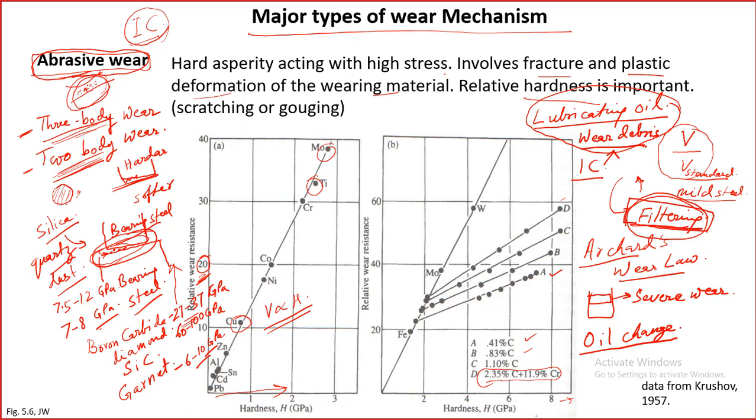Not only wear debris, but there are also some thermal products, some degradation of the oil molecules, and therefore the oil actually changes its color from very golden color to very blackish color. A very new engine oil will look, well, I'm talking about for the car, but some other colors are also used. For automotive car here in India we keep the color as golden, and this will become like black. I think for motorbikes the oil is red in color, but again it will turn into black. So that's why we need to do the oil change.